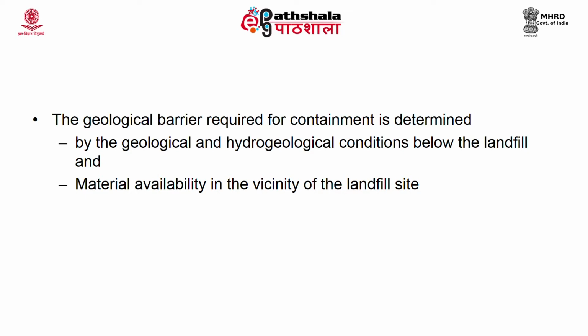This will influence the design. For example, if the place where your landfill is located has soil with a high porosity, then you have to have a liner material which is more secure, so that the leachate does not enter into the soil. Once there is leakage, if the leachate enters the soil, sandy soil will be more porous and the leachate will easily percolate and reach the groundwater. So, you have to keep that in mind. The geological and hydrogeological conditions are very important when you select a geological barrier.